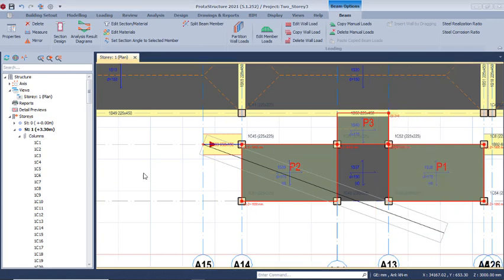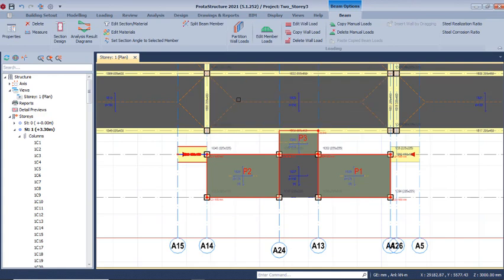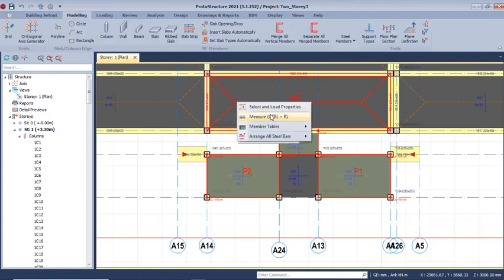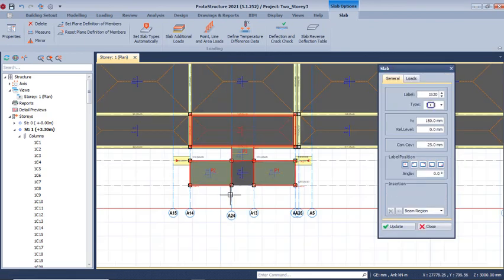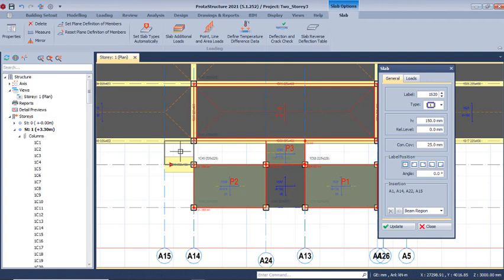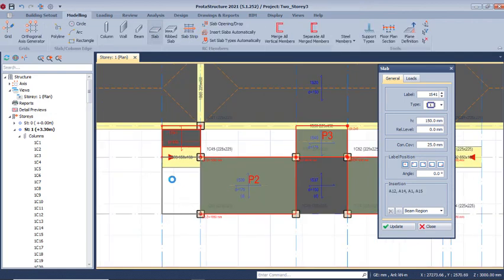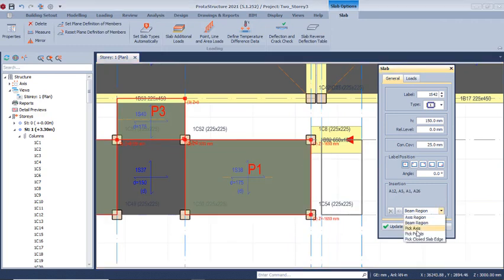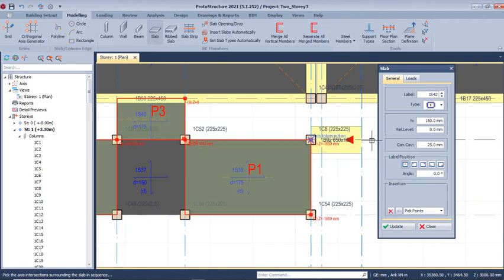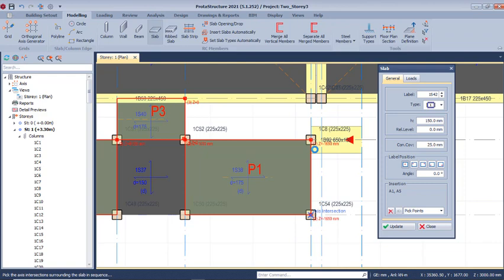So close this. All right, so having done this, what you just have to do is select the slab we are having here, then right click, and then its property. At this point we are going to place it in this provision where we have the intersections of the grid lines bound together. So you place the slab like this, and in these provisions we're going to use another pick point option so that we can select it successfully. We'll pick the first point, pick the second point, pick the third point, pick the first point, and then we'll place the slab just like this.